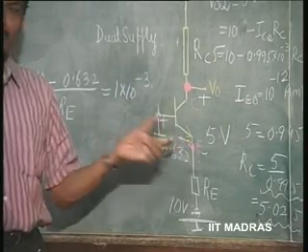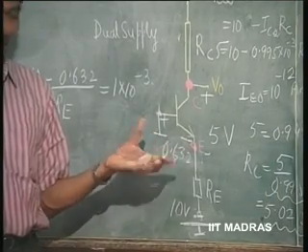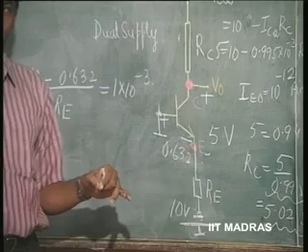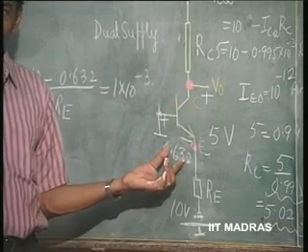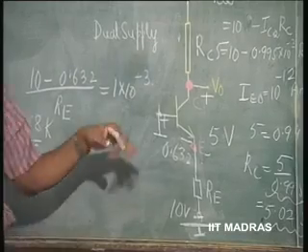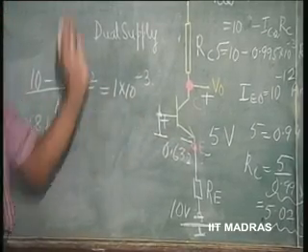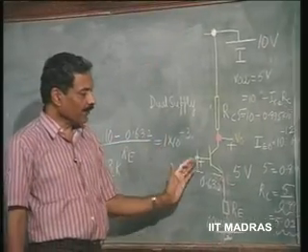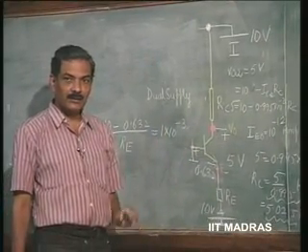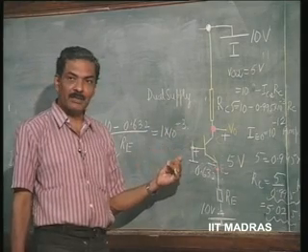That is, emitter current is very sensitive to this voltage. So, if this voltage changes even slightly, it will change drastically, and this voltage of 0.632 is difficult to obtain exactly. So, instead we ground this and connect a base resistance and apply it to the positive voltage 10, so that the base current gets fixed, in which case collector current or emitter current will be dependent upon the base current.